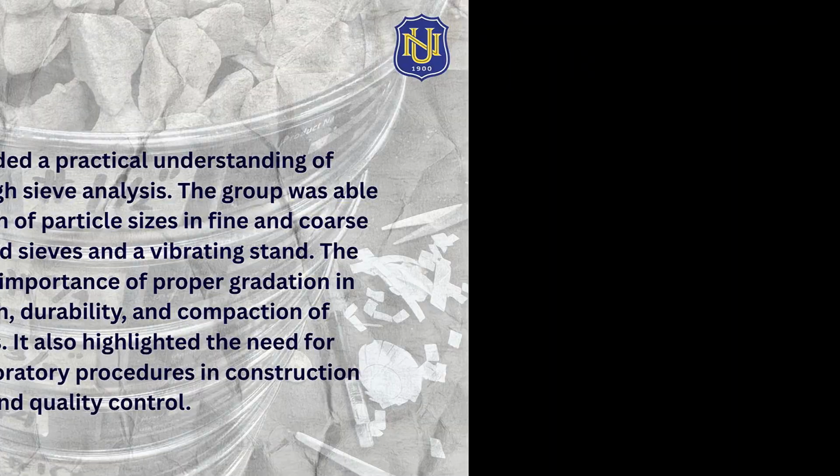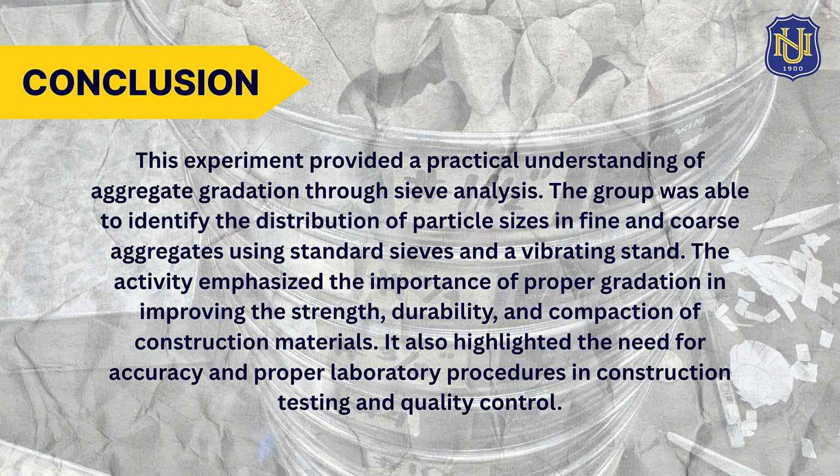of the aggregates. In conclusion, this experiment provided a practical understanding of aggregate gradation through sieve analysis. By separating fine and coarse aggregates using standard sieves and a vibrating stand, the group was able to observe the distribution of particle sizes in the samples. The experiment highlighted the importance of proper gradation in achieving better compaction, strength, and durability of construction materials. The activity also emphasized the value of accuracy, proper testing procedures, and correct handling of laboratory equipment.